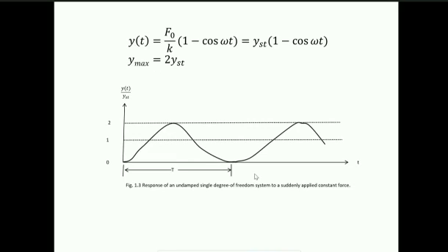That means at time equal to TD, you calculate the displacement and the velocity. Once you know that, those will be the initial displacement and initial velocity for the free vibration, because the load has been withdrawn, for the free vibration which will occur during the next part of the time.